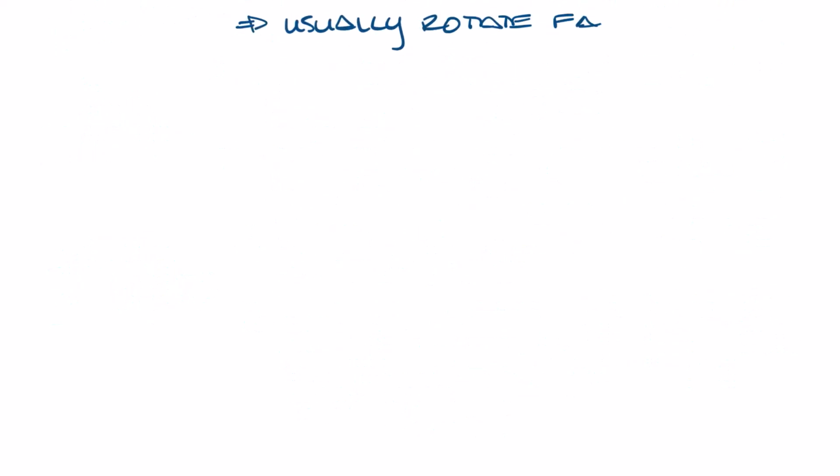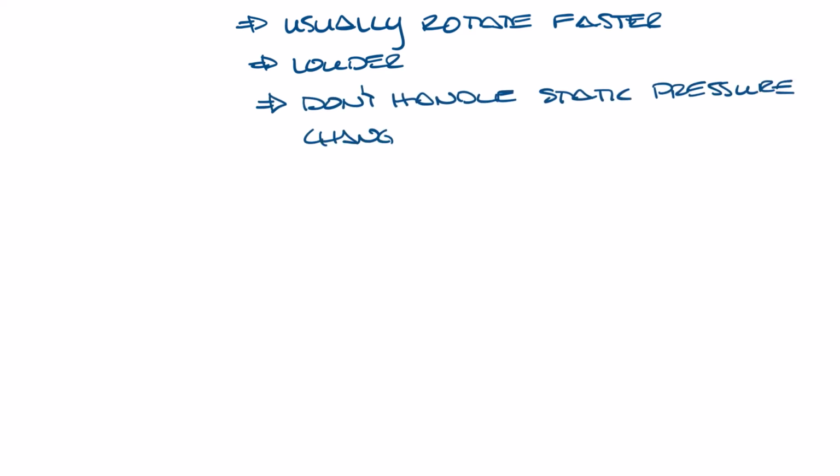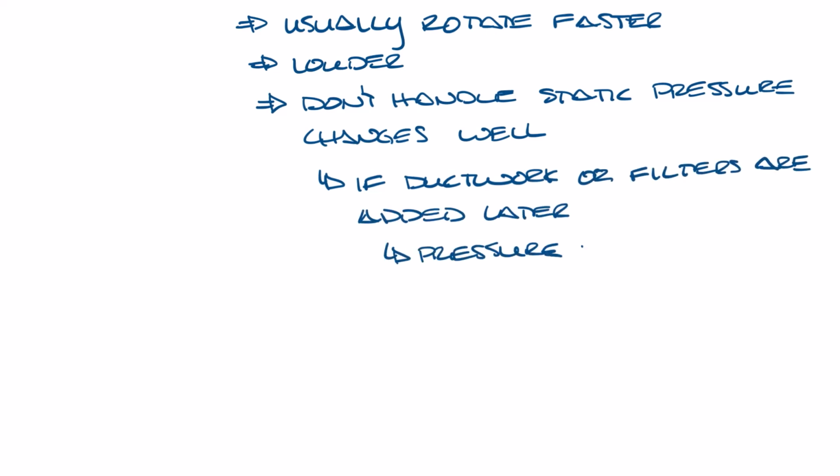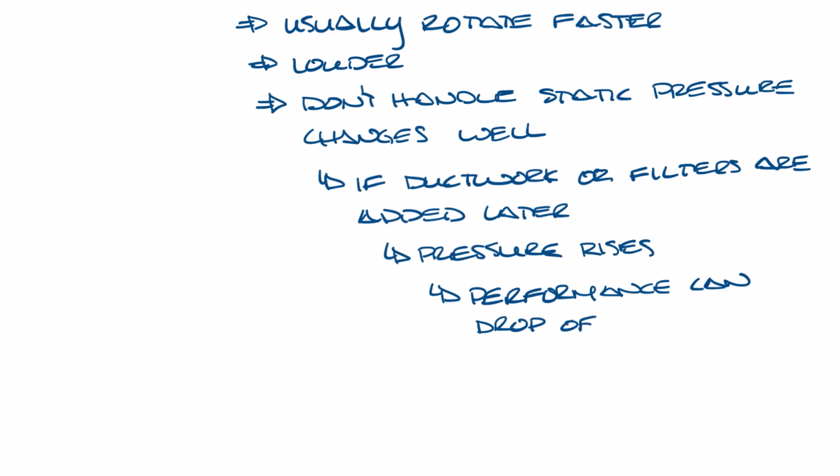They usually rotate faster and are louder than centrifugal fans and don't handle static pressure changes well. If ductwork or filters get added later and the pressure rises, an axial fan's performance can drop off quickly.